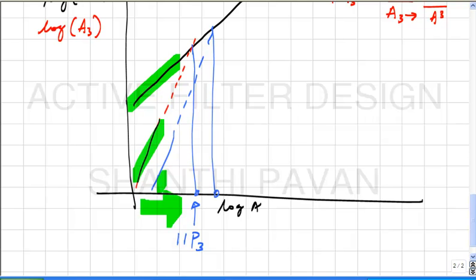The only relevant, or rather sane, measure of nonlinearity is intermodulation distortion. So whenever you go into, for example, RF or wireless systems, nobody even talks about harmonic distortion. It's totally irrelevant, for the reasons I just mentioned. All nonlinearity is quoted using intermodulation measurements, where you put in two closely spaced tones. That's easy to do, right?